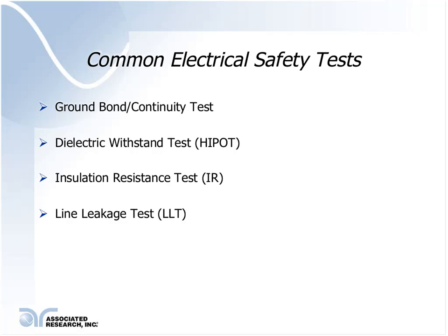But before that, let's just go over the 4 common electrical safety tests: ground bond and ground continuity, dielectric withstand test, also known as Hipot test, insulation resistance, and line leakage test.